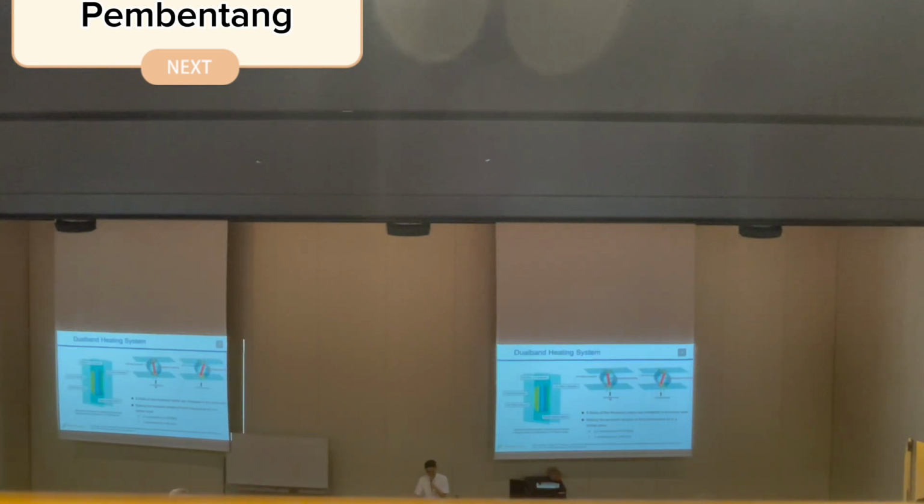If fields of two frequency bands are irradiated into the same area, to make the resonator lengths for both frequencies be of a similar scale, we use lambda over 2 resonators for 915 MHz, which has longer wavelengths, and lambda resonators for 2.45 GHz, which has shorter wavelengths.